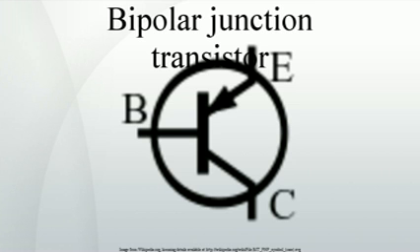Punch-through. When the base-collector voltage reaches a certain, device-specific value, the base-collector depletion region boundary meets the base-emitter depletion region boundary. When in this state the transistor effectively has no base. The device thus loses all gain when in this state.